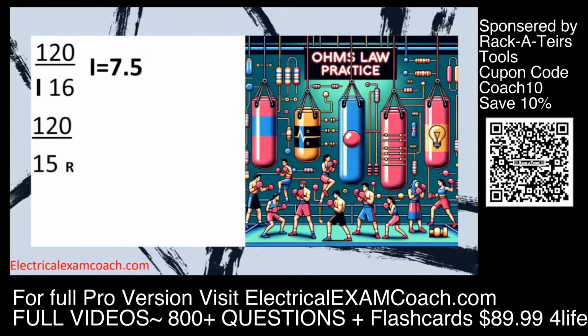We have 120 volts. We have 15 amps. What is the resistance on this circuit? That's right, it's 8. Great job. All we have to do is take 120 divided by 15, and that lets us know that there is 8 ohms of resistance on this circuit. We have this scenario, and we're solving for voltage. We have 4 amps and 69.25 ohms of resistance. We multiply 4 by 69.25, and that lets us know that we have 277 volts on this circuit. Great job.